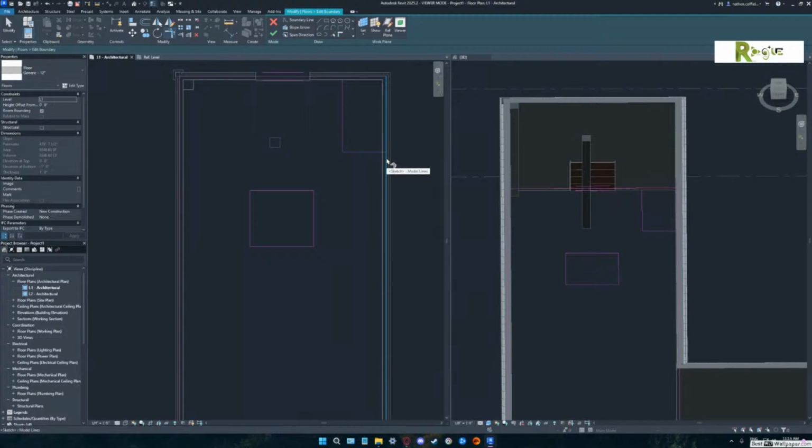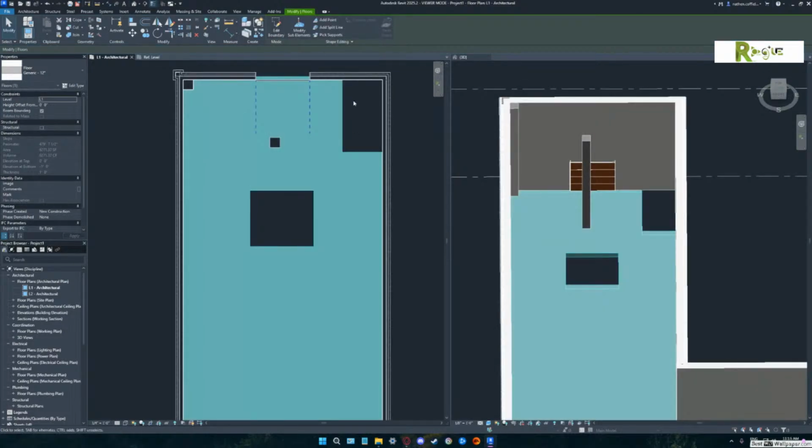There you go. And then do that same thing up top. It's going to cut away outside of the two clicks. Nope, the other way. See how it did that? Oh, okay. I got you. So trim, select wall. There you go. Oh, sorry. I got you. And then hit the green checkbox and you're good. Okay.